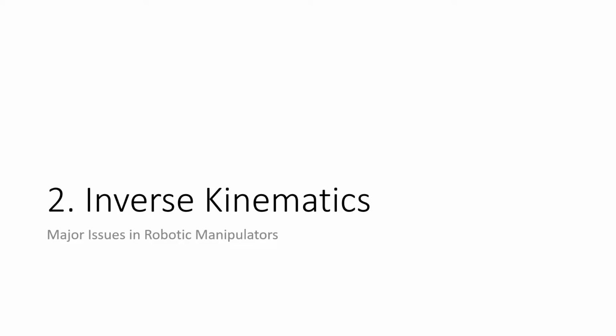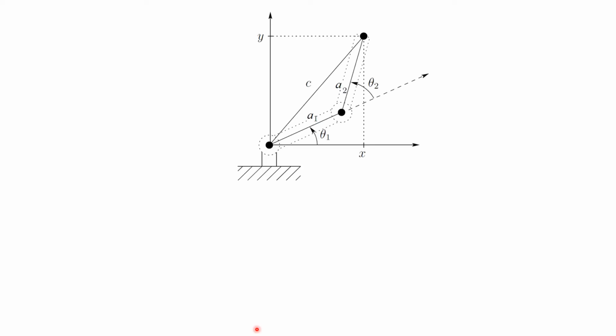And the second problem was to find out the inverse kinematics of the manipulator. In that, we were able to identify, if we know where the end effector should go at the next instance of time, what should be theta 2 and theta 1 values, given as reference to the individual joint controls. We wanted to have these expressions, and these expressions were derived last time, and interested listeners can refer to the previous lecture as well.